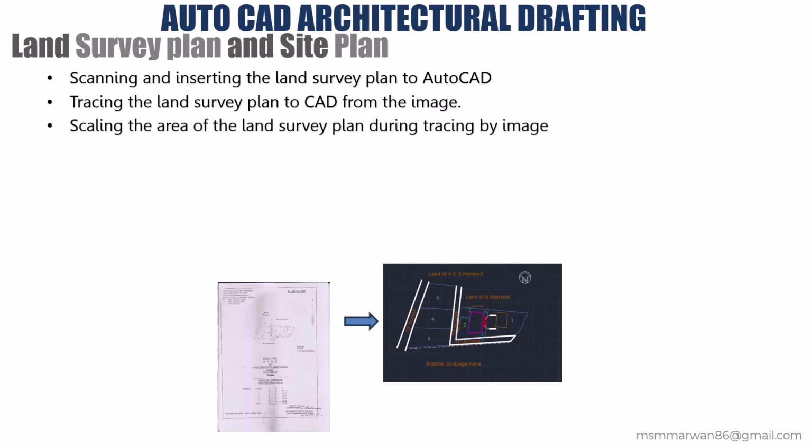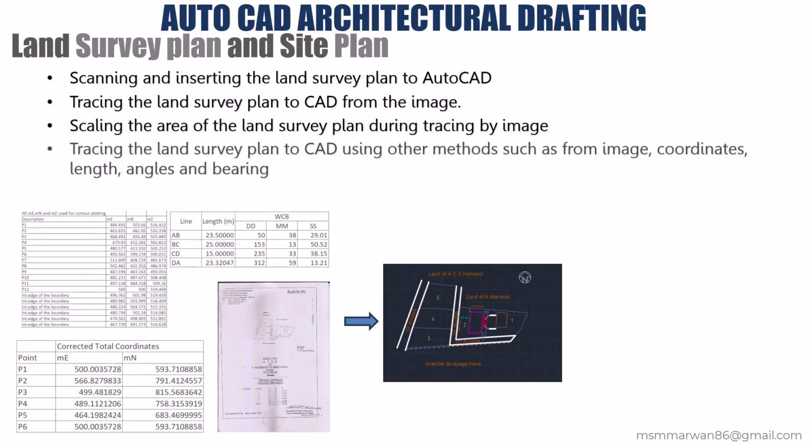And also, after completing this exact land survey plan with CAD lines inside AutoCAD software, we have to check the area. So how do we scale that exactly to the correct area? Those things we are also going to study. And not only the image format: if you have it in any other mathematical format like coordinates, east and north values, x and y values, or sometimes lengths and bearing angles, whatever the format, it doesn't matter. We should know how to take that into CAD and proceed with the work.